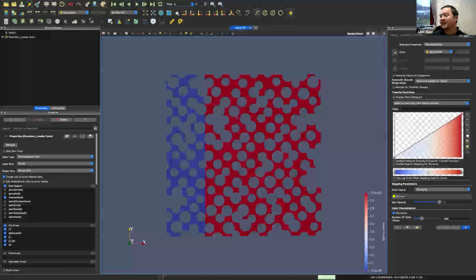That would be the best way of modeling this. Now the problem, of course, is you're going to have a lot more cells too, and it's already slow. Sure. Multi-phase is hard. If you see what you've done with single phase, it took a few minutes. When you do a real image, this is a micro model, and it takes a long time because it's hard. So you're going to want to save as much computational time as you can anywhere you can. Right.